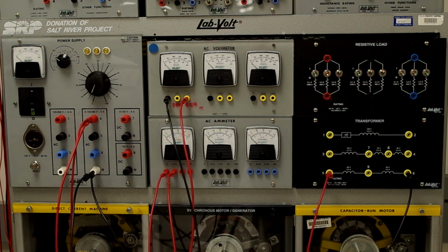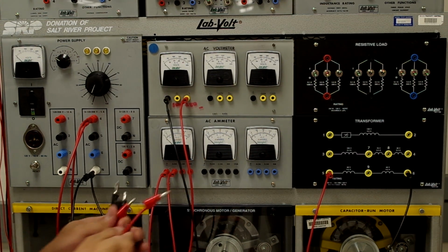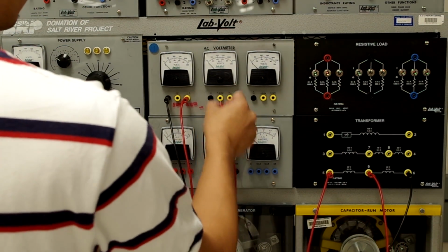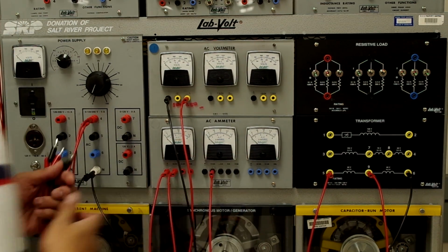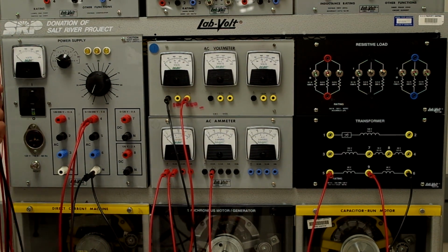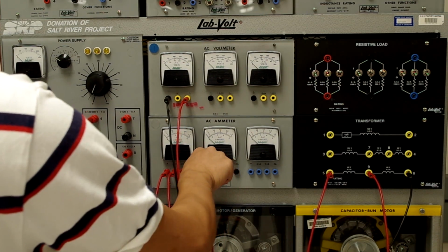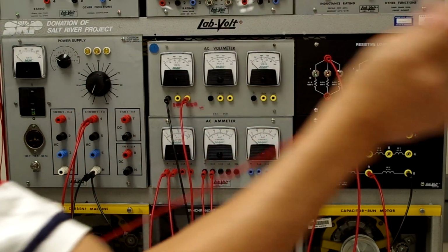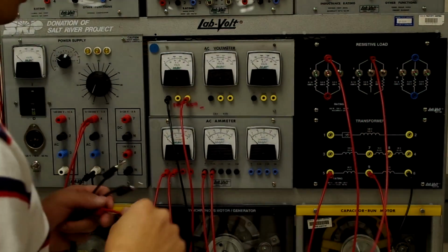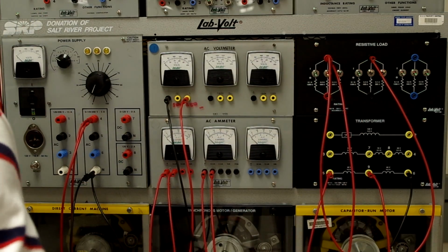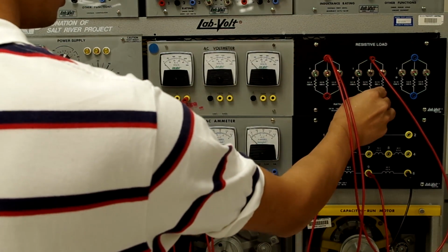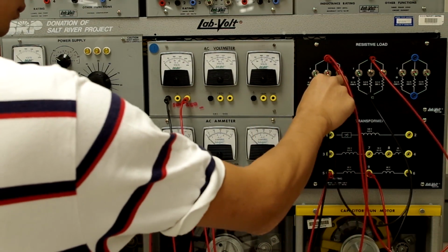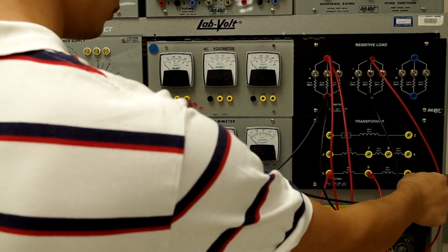Now we're ready to connect the load from the midpoint of the auto transformer through an AC ammeter, and from the AC ammeter to a resistor. And in this lab, in order for us to get the proper resistance value in the analog hardware lab, we're going to have to connect two of those resistors in parallel. So we're going to connect the neutral point of the resistors together. And now that those are connected, we're going to connect that neutral point to the neutral point of the auto transformer, which is number 6.